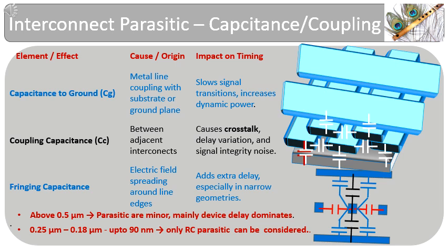Interconnects are the physical wiring structures that carry electrical signals and power between various functional elements. Structurally, an interconnect consists of metal layers, vias, and dielectric materials. The interconnects are not just physical wires but functional elements that define circuit timing, power, and noise behavior. These layers, due to their electric fields, create parasitic capacitance between the interconnects. The geometrical parasitics created are of three types, namely, area, overlap, and sidewall capacitances.